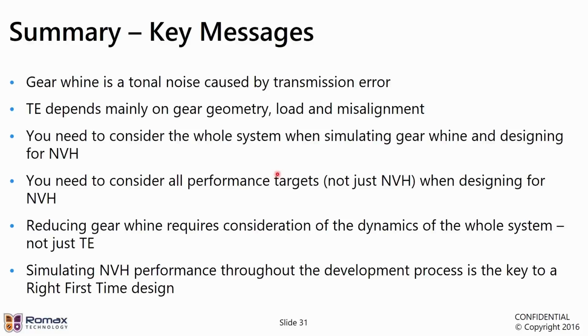We've seen that gear whine requires us to consider the dynamics of the complete system. We're not just looking at the gears and TE. That is an important part, but it's not the whole story. We need to look at the dynamic response of the whole system, because that ultimately is where our targets are going to be defined and how we're going to decide whether we have a successful transmission or not. And we've seen how simulating the NVH performance throughout the development process, right at the beginning all the way through to the detailed design, is the key to having a right first time design that gives us a higher quality design, cheaper and faster than we would otherwise be able to do.